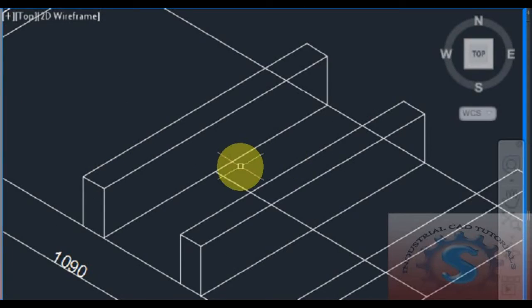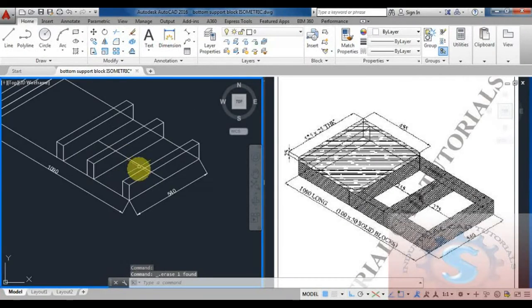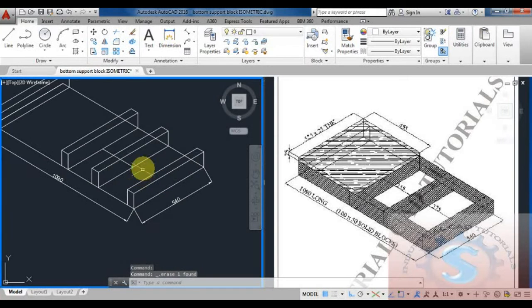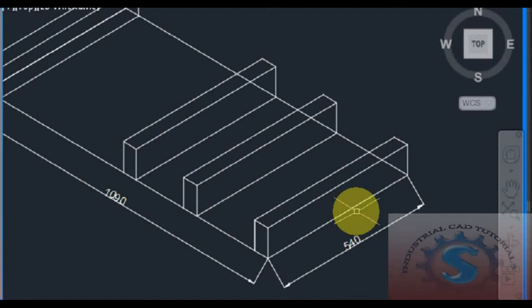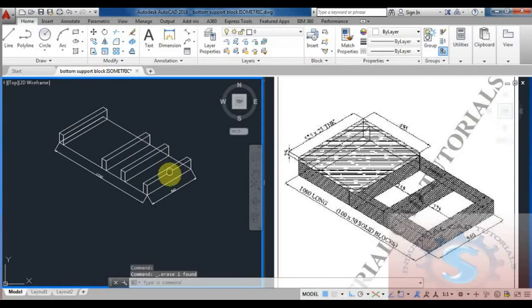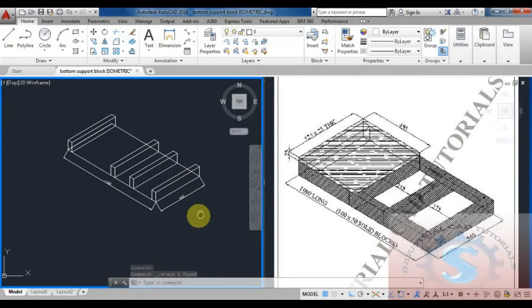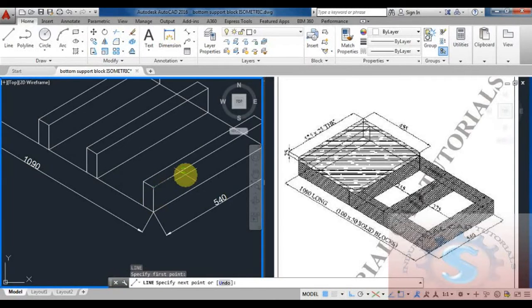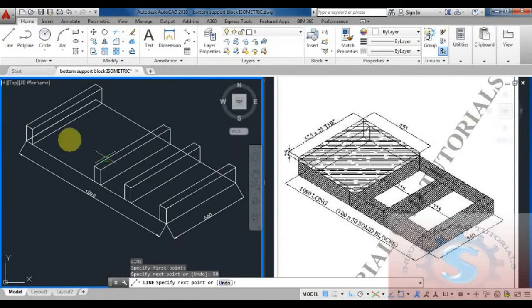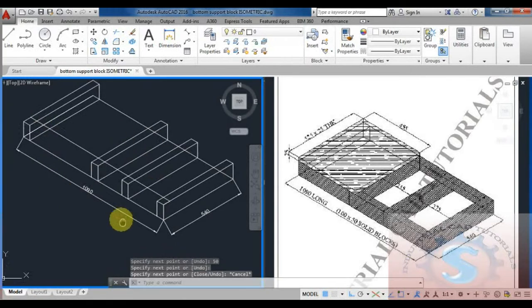And the operations I perform are the line operations, see, delete and move, trim, extend. The simple operations I'm performing by using the isometric. For isometric, you can turn on the isometric snap by using the Osnap settings and change the cursor by using the F5 key. See, already the 4 blocks are completed.